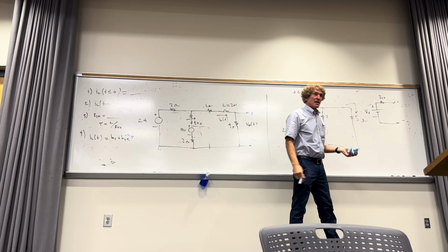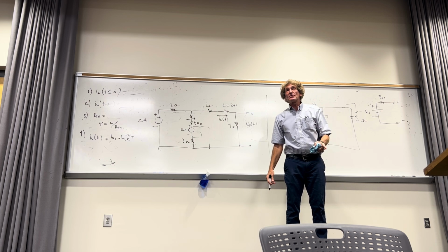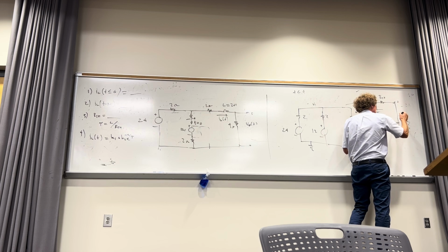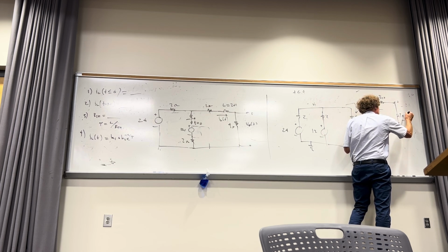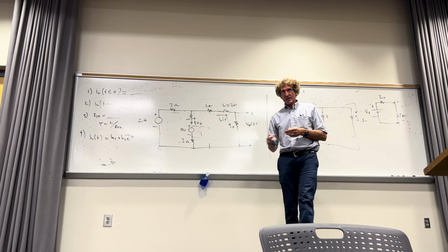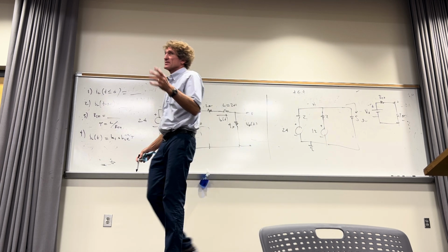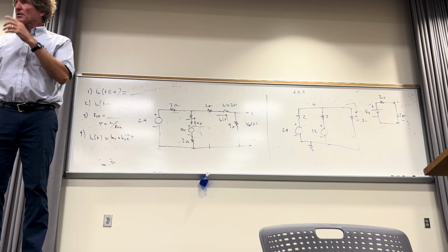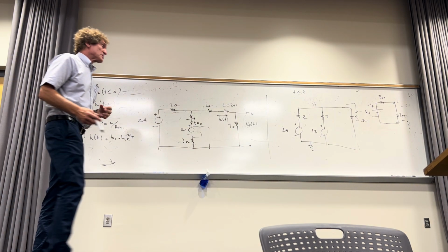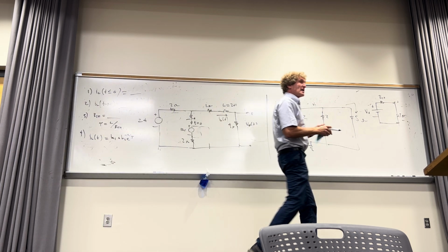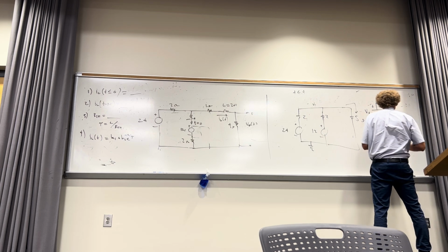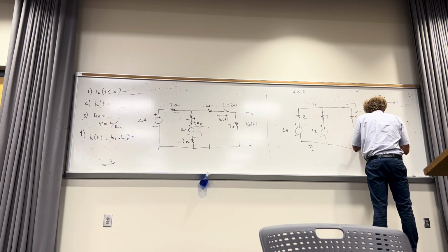You all see that? What that is identical to is finding the short circuit current here. Short circuit current would be, if you just did that. What is the short circuit current there, by looking in terms of the voltage and resistance? Class? Just the voltage divided by the resistance. Do you all agree? That's what short circuit current means. I can say that this is exactly identical to this, and then I think you'll see why.